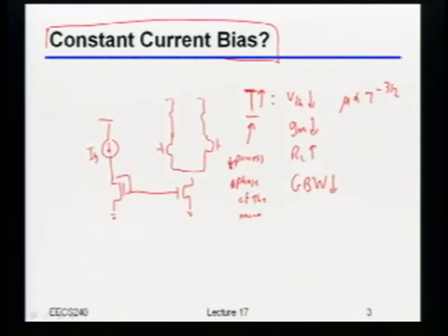No. It's great that I know what the current is, but that doesn't necessarily give me the amplifier I actually want. This is an example. It doesn't give me a constant gain bandwidth, or even a constant gain, because depending on what the load resistance did versus what the GM did, the gain could even be shifting.